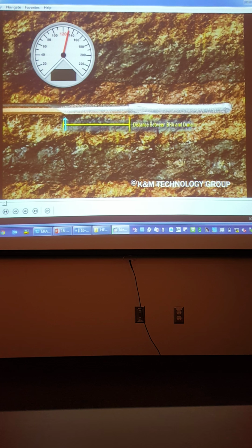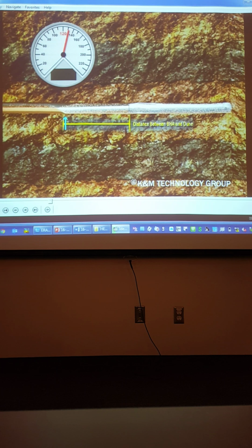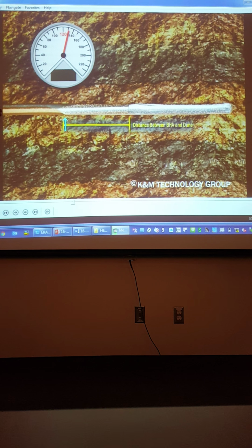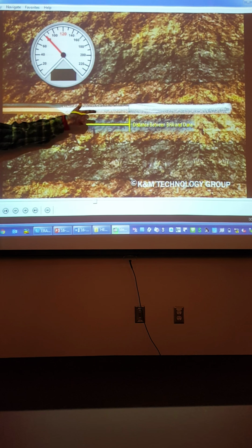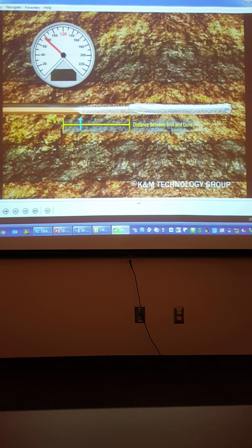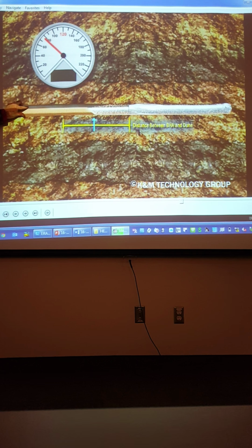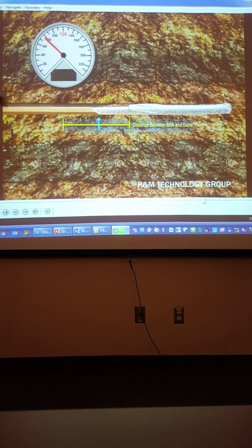So when you're drilling along and you have high rotary speed, your dirt is hopping and skipping and jumping on the bed above the BHA. You don't have a hole cleaning problem around the BHA itself, or even some distance above the BHA, a matter of distance before the dirt falls out. But when your rotary speed drops too slow, then this bed height just starts building and building and building because you're not moving that upper layer.